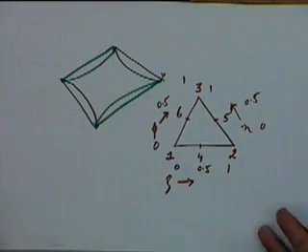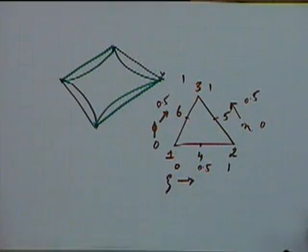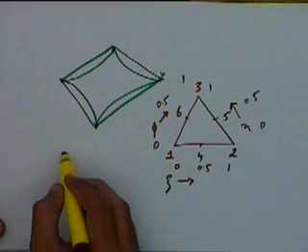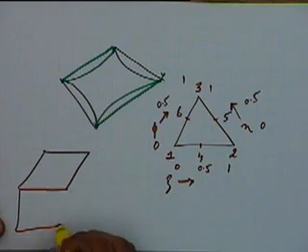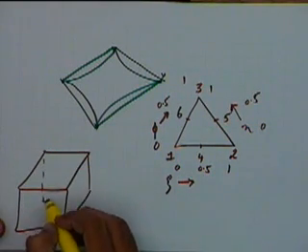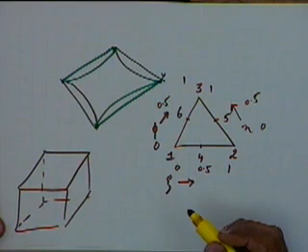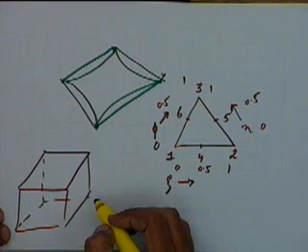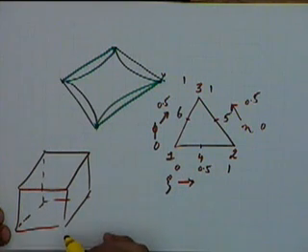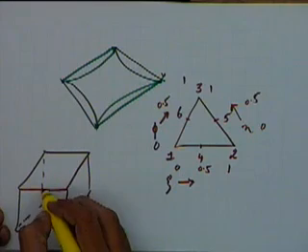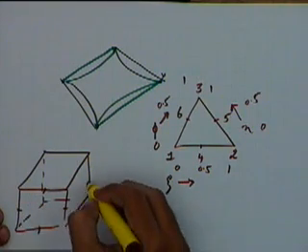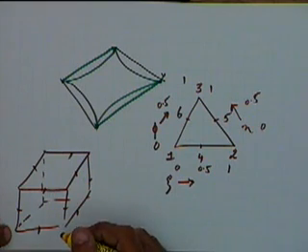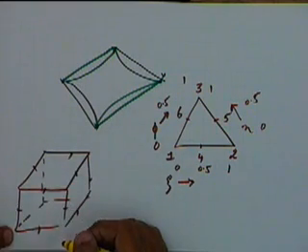Okay, and the same ideas can also be extended to 3 dimensions. Right now we have talked of an 8 noded quadrilateral element. We can define a cubical element. First we can define an 8 noded cubical element. Then we can define a 20 noded cubical element. At the center of every edge we can have an extra node, and so on. So 12 edges give us an extra 12 nodes. You can have a 20 noded cubical element.